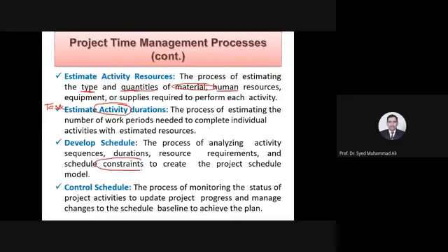Constraints. There will be certain constraints. Unless and until the result of the 7 days cylinder strength is there and it is satisfactory, you will not be able to move to the next level of concreting on the first floor. You have to wait for that. So various constraints can be there. Some days are off, some days are working, and so on.